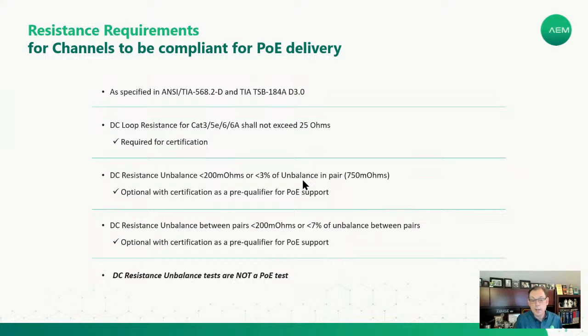Now, one note here at the bottom, I touched on this earlier, but a DC resistance unbalance test that we're talking about here is not a PoE test. If somebody's telling you that a DC resistance unbalance test is a PoE test, that's not the case. It is essentially a pre-qualifier to make sure that the cable is ready for PoE and that it's going to be compliant for PoE delivery.